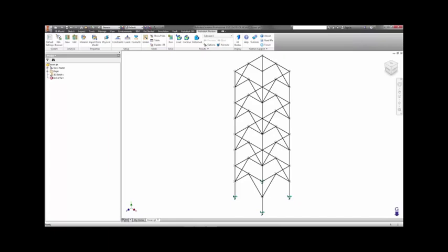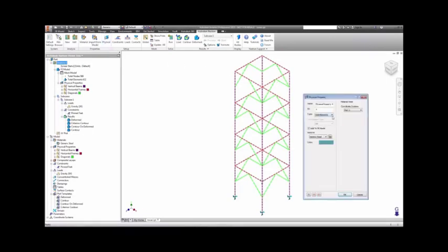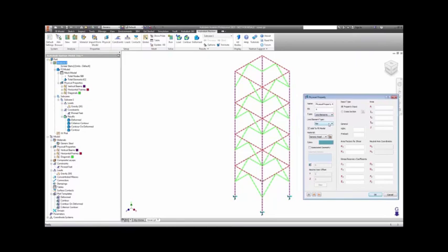During this video, we'll discuss the speed and improved accuracy of using beam modeling capabilities on a tower model, showing how cross-section or geometry optimization is easily accessible for all engineers. Instead of the solid elements that are normally used, we will mesh the model with line elements chosen here in the property dialog.